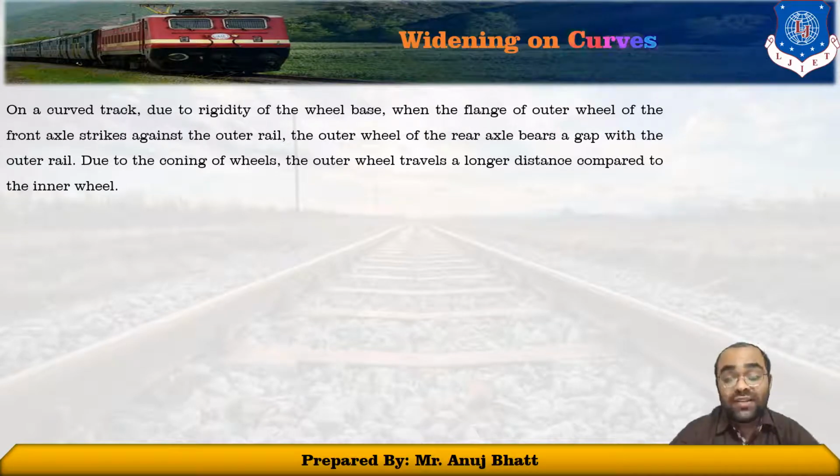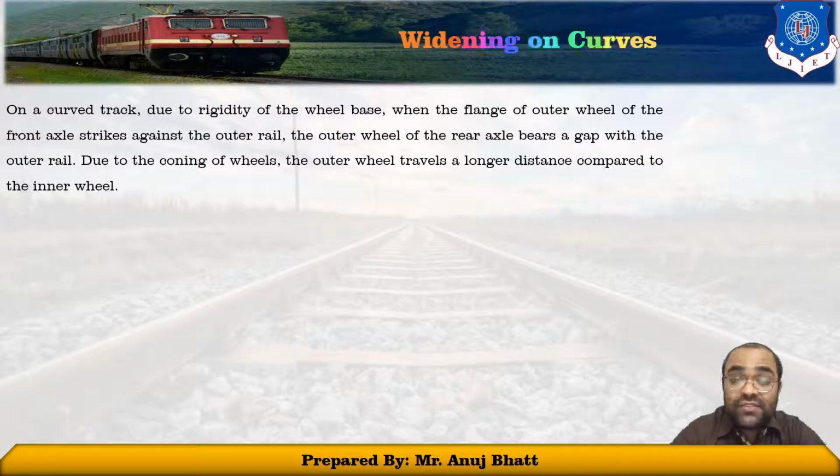Well, a close study of the running of vehicles on curves indicates that the wear of the flange eases the passage of the vehicle around the curve, and as it has the effect of increasing the gauge, this widening of the gauge on a curve has in fact the same effect and tends to decrease the wear and tear on both the rail and the wheel.